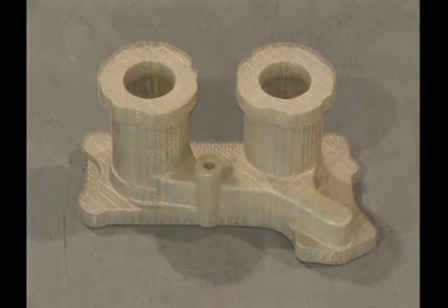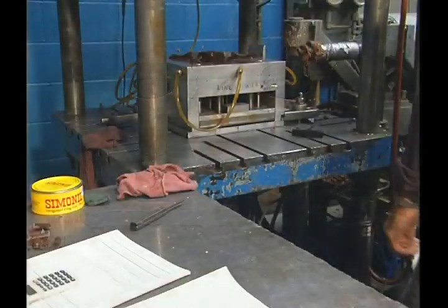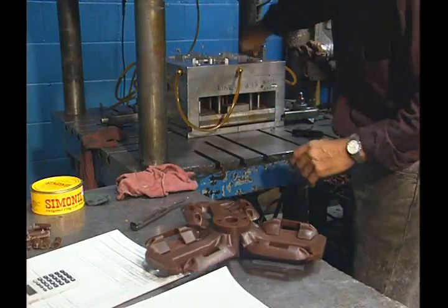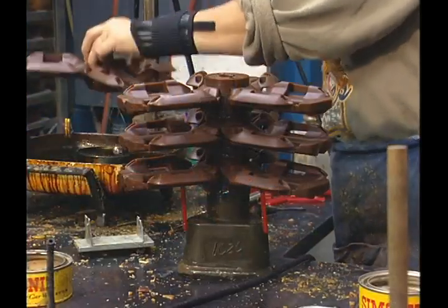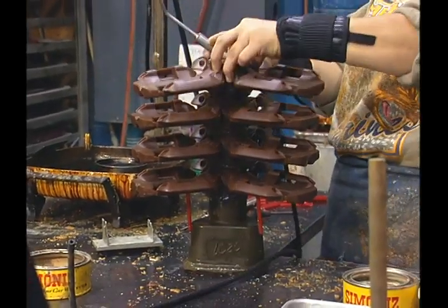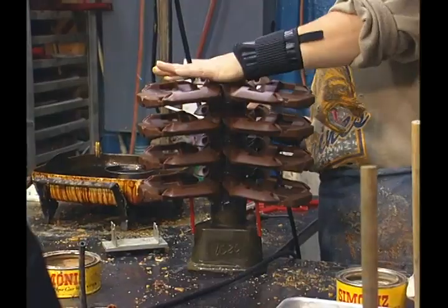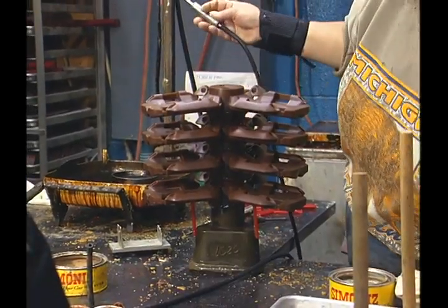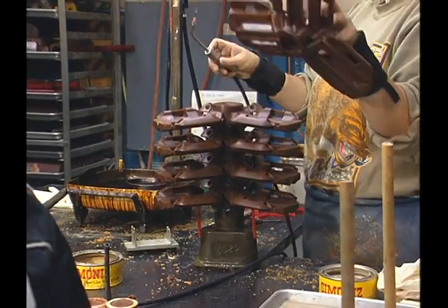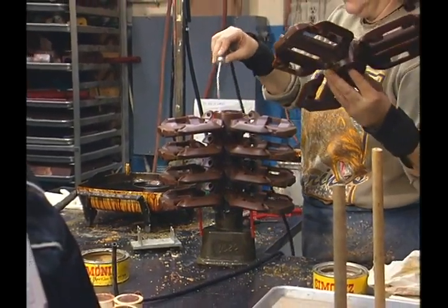Consumable plastic patterns are also used. Investment casting patterns are made by injection molding. These patterns are assembled onto a wax post connected to a pouring cup. This pattern assembly, called a tree, usually incorporates complex runner systems to assist metal flow in the investment casting process.